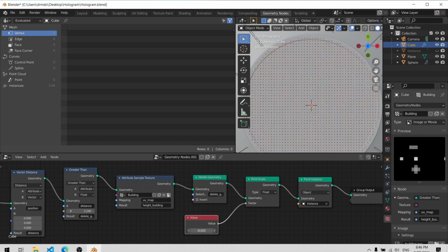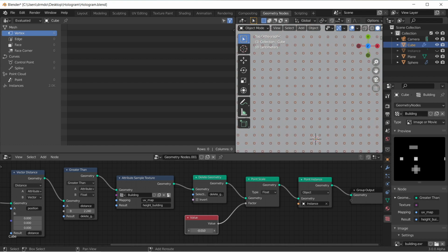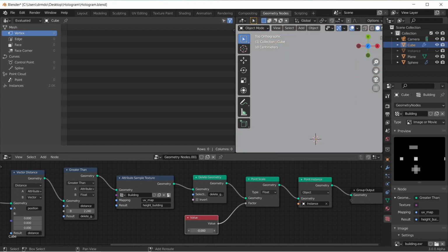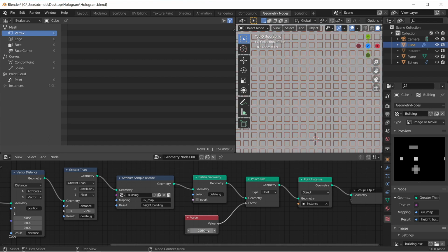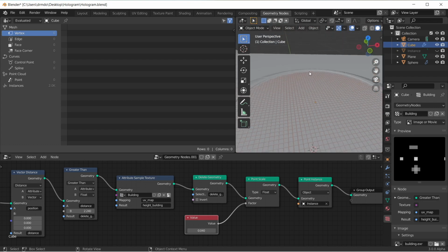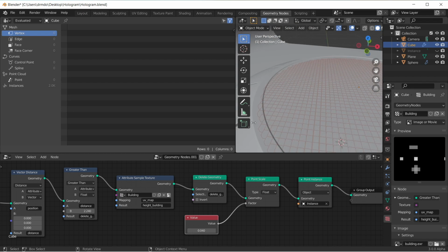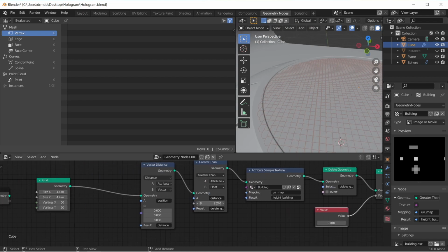So I want the relative height of my cubes to be such that the cubes are perfectly tessellated. So let's try 0.03. Let's just get it approximately correct. There you can see I've got a whole lot of cubes there, and they've been cut off at a certain radius. Let's actually bring that radius down a little bit.